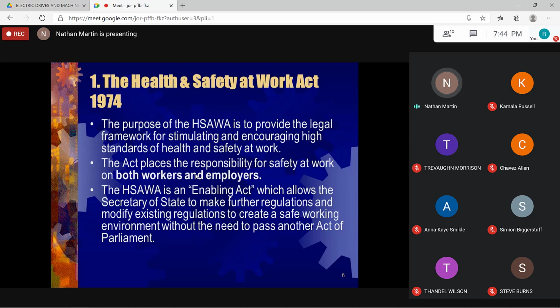So when you wrap the conductor clockwise around the screw and tighten, it aids in pulling the wire under the screw. When you wrap it anti-clockwise and you tighten clockwise, the force pushes the conductor from under the screw, right? So this is a code of practice, something that we learn over a period of time, and it's passed down through the ages and we practice.